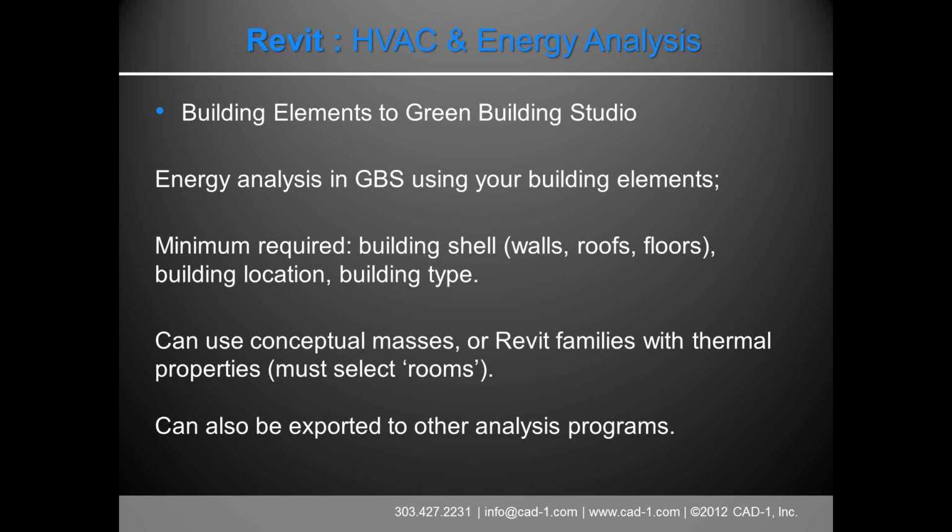And you can use conceptual masses, which I consider the first of the three types. You could consider both of these the same type, kind of semantics. Or you can use your Revit families that are in your file with their thermal properties. What's new in 2014 is the ability to put thermal properties, R values, U values, with your building elements. So if those values are in there, you might want to take a look at using those. If you have not added those thermal properties, then you probably want to stick with just the building elements, and there's a couple places where you can override that.